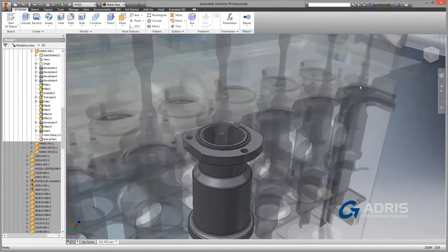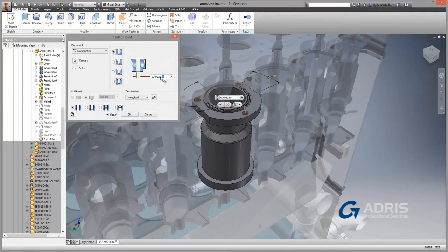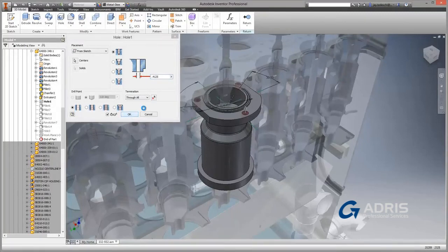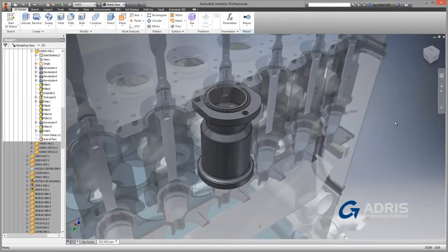So we've drilled down into this single component. We're now editing this component. Again, Express mode. So let's pick the hole. We'll edit the hole itself. Let's just change the size of that. So update to the hole size. Again, I'm going to point it out. Fourth time I've said it, still in Express mode. So we edit the hole, all of the holes on all of these same components, update to the entire assembly. Now we'll go ahead and finish the assembly and then back out.